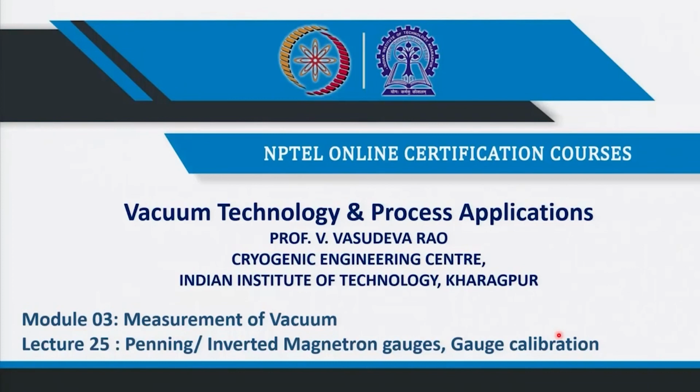We have seen Bourdon gauges, which are standard mechanical gauges of high pressure, extended towards this side. So, all these gauges we have seen for different purposes. They have sensitivities, ruggedness and ranges applicable at various levels of vacuum. But now our game is towards high vacuum, ultra high vacuum. So, there we have seen the Bayard-Alpert gauge in the last class, how ionization is used.